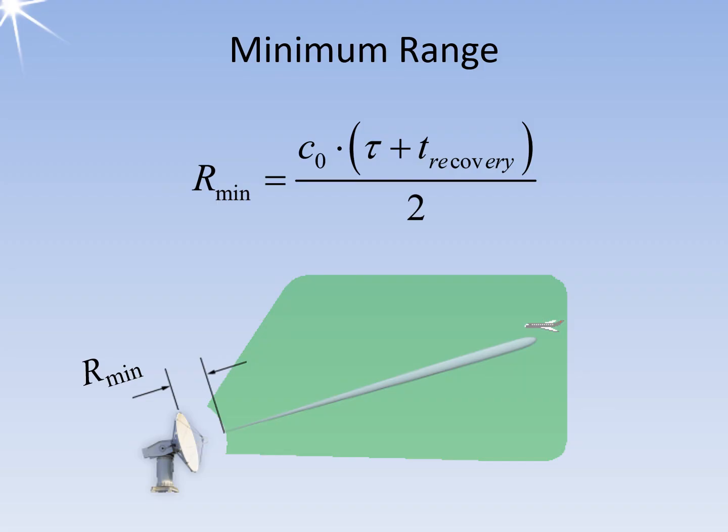Another possibility for the occurrence of the minimum possible range is when the radar antenna is located on an elevated site and cannot radiate directly downward. Therefore, a blind spot arises, and on the surface, there is a range of distance that cannot be monitored. This case occurs with coastal surveillance radars and naval navigation radars mostly.